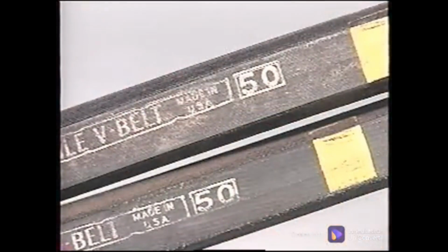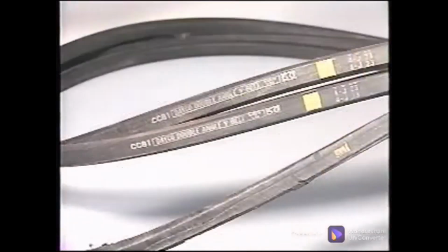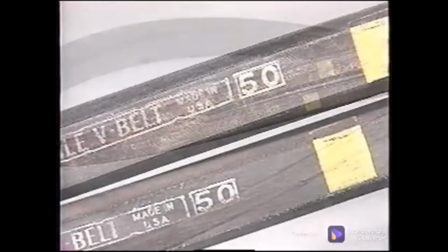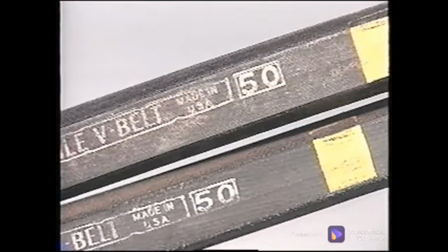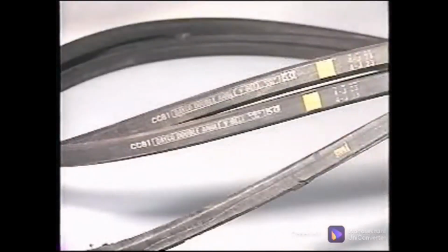Although belt manufacturers have much closer tolerances than they used to, there can still be some discrepancies from one run to the next. Some manufacturers mark the belts so you will know if you have matching belts. For example, the belts from this drive show the belt size, the manufacturer's name, and then the number 50. If a belt is 1/10 of an inch longer, it would be labeled 51 and so on. If it is 1/10 of an inch shorter, it would be labeled 49 and so on. Since all 3 of these belts have the same number, they are a matched set.